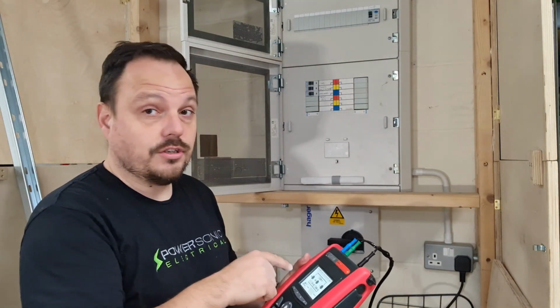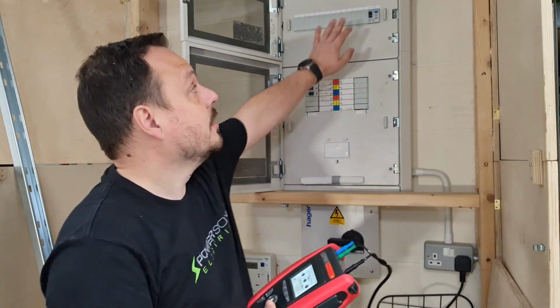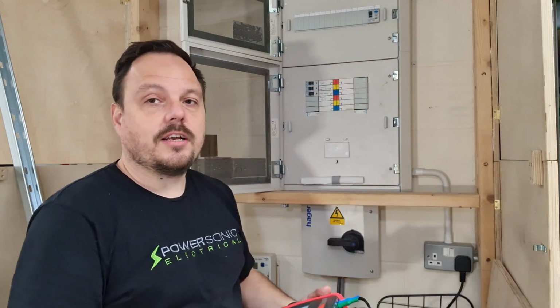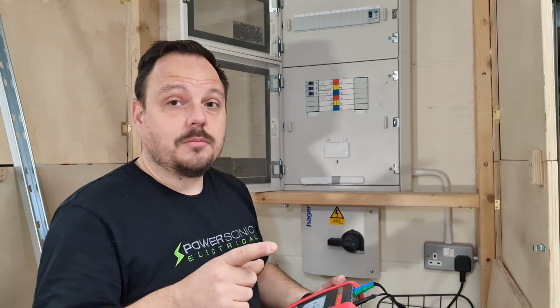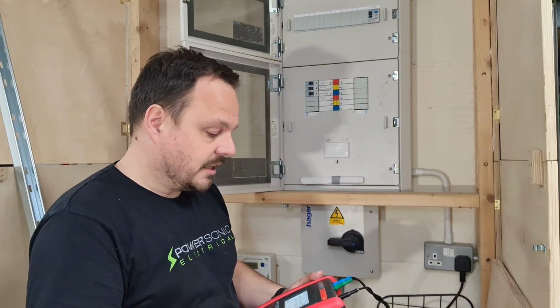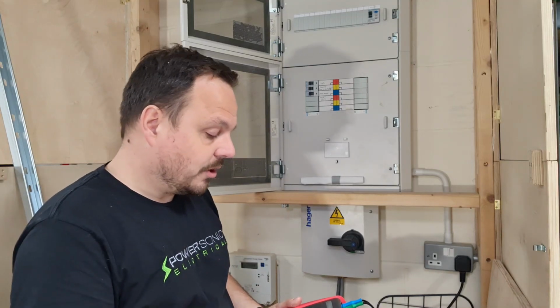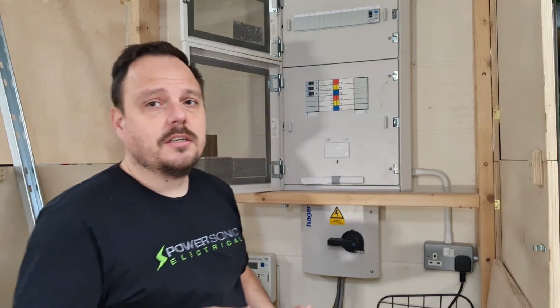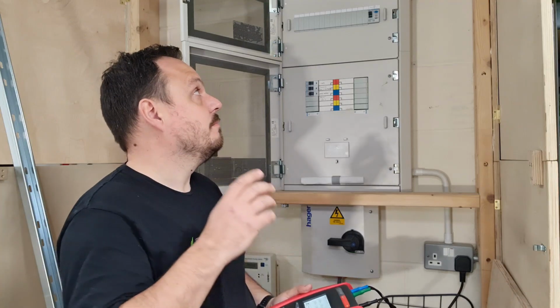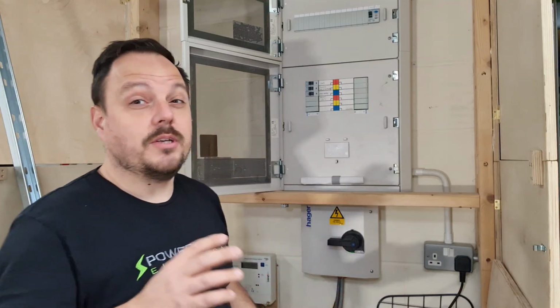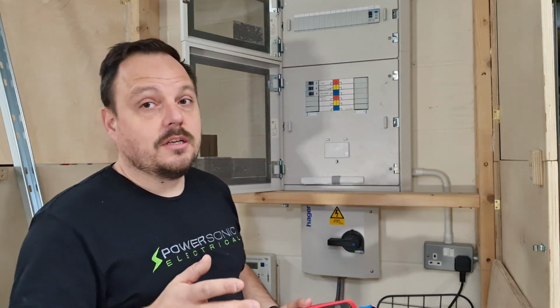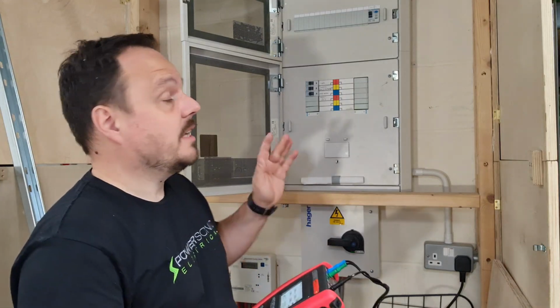Important now that I set it to no trip on the RCD range, because we do have this RCD up there looking after the socket circuit, and I'll speak a little bit about that in just a minute. But let's get the test result from this socket, just so you can see me obtaining a result at least once. Now obviously when it's doing the measurement for earth fault loop impedance through an RCD, we know that they can increase the value that we're recording due to impedance in the RCD itself.